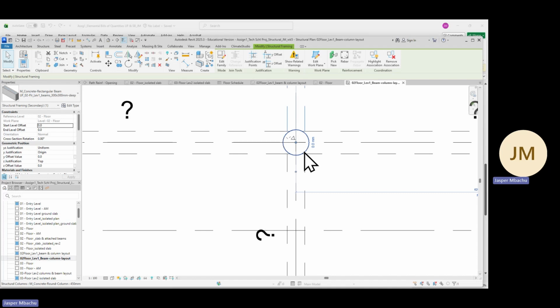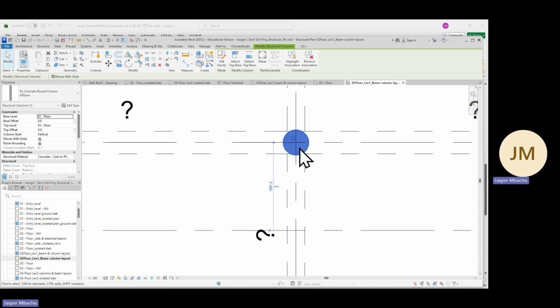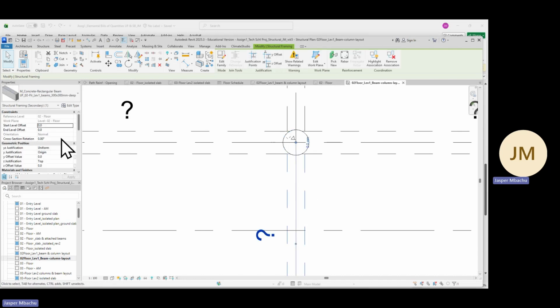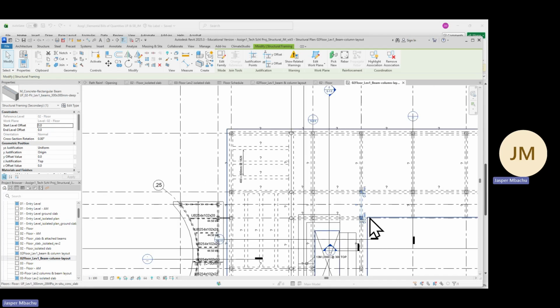Click on this column, because the column marks the beginning and the end of every beam. So if we are doing it manual measurement, we can identify the length of these beams to measure them manually. Okay. So if we click on those columns too, they are called structural columns. So in our VG, we're going to leave out structural columns, and we also going to leave out structural framing to isolate every other thing that is in there.